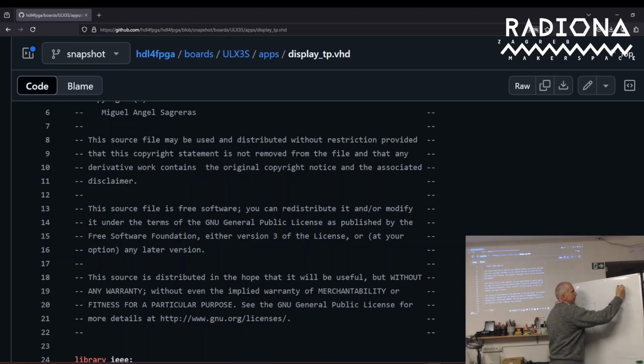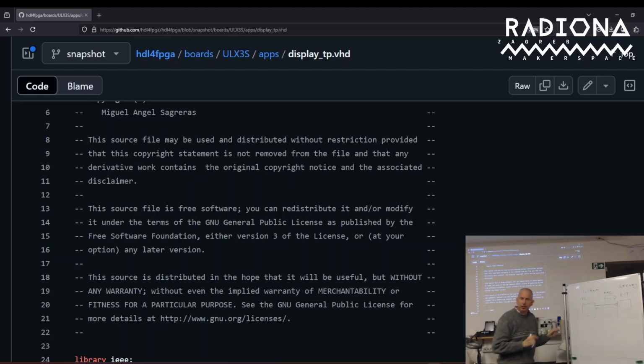This is the server, and this is the client. So when the PC sends the packet, the Ethernet will be here. So there is no problem. The kit will take this MAC, swap the source and destination, and then we send it back to the PC. So you can have several PCs sending to the kit, and the kit will respond to the PC.